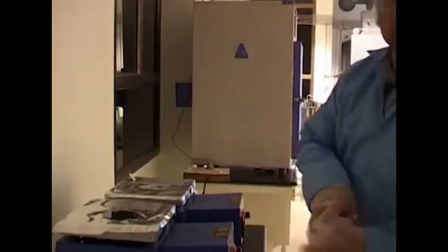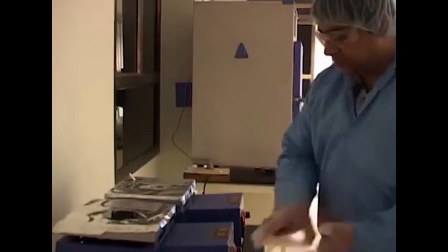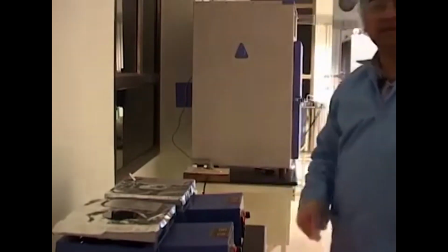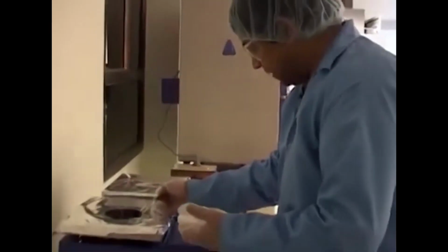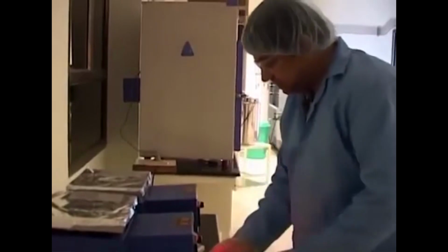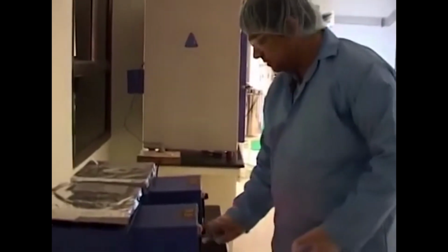Again, we have to equilibrate it to a room temperature condition and then put it back into the 95 degree step, so that we can have properly exposed and cured photoresist film. So time is up really now, and so we should take it back again, put it back into its resting place, and then wait until this equilibrates to the room temperature, and go back, do a 6 minutes heating step in the next temperature step, that is 95 degrees Celsius.